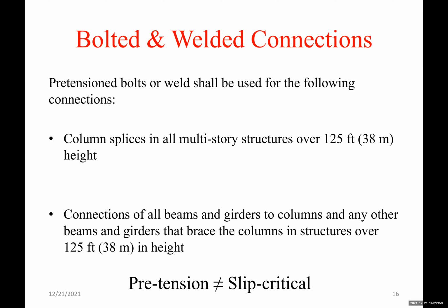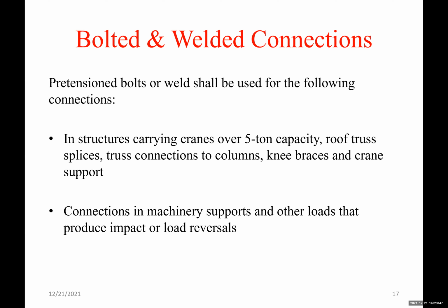So that's pretensioning, but pretensioning does not mean it's slip critical. We can use, or sometimes we have to use, pretensioning with bolt bearing type connections, and of course that depends on the type of the bolts that you're using, such as F1852 bolts, F2280 bolts. Those are called twist off bolts, which is basically a way of pretensioning, but these are not used for slip critical. Those are used for bearing type connections. So we don't have to use slip critical if we use pretensioning. This is very important because there's a misconception about that. Okay, if it's pretensioning, it's slip critical, or slip critical, of course, has to be pretensioning.